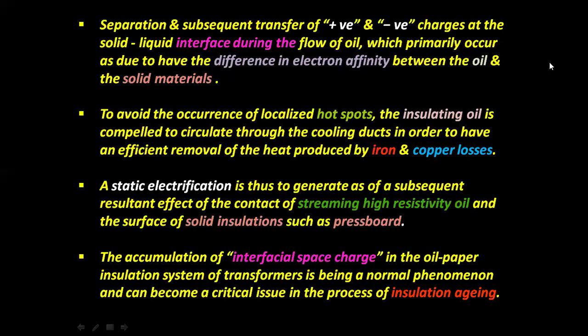To avoid the occurrence of localized hotspots, the insulating oil is compelled to circulate through the cooling ducts in order to efficiently remove the heat produced by iron and copper losses. A static electrification is thus generated as a resultant effect of the contact of streaming high resistivity oil and the surface of solid insulation such as pressboard.